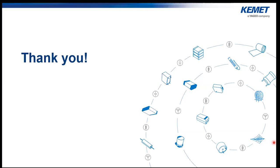So it depends on the ESR of the device and the capacitance, and how much further away those interconnected particles are from that tantalum wire. And I guess to answer the second part of that question, which sounds like decoupling, yes, we do recommend using multiple types of components together for decoupling applications. If you use KEMET's KSIM tool, you could actually simulate the combined impedances and ESRs of the devices.